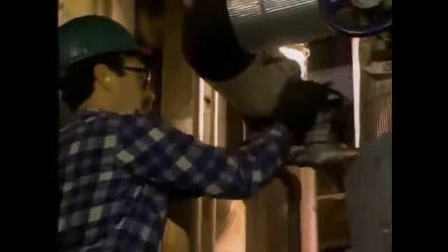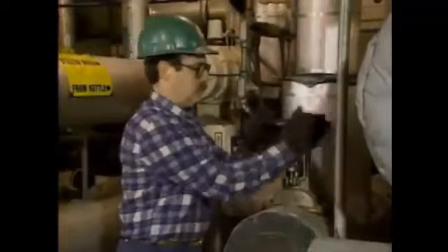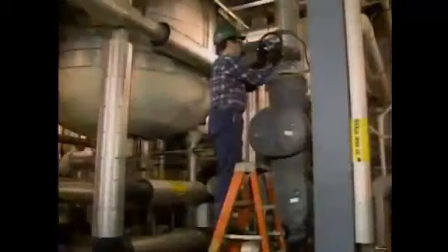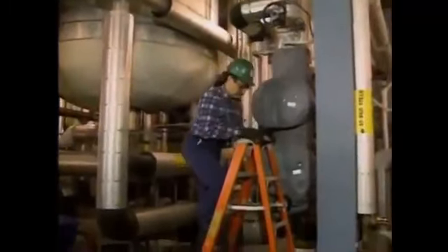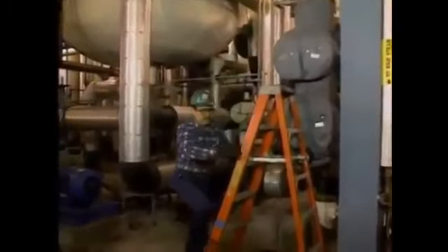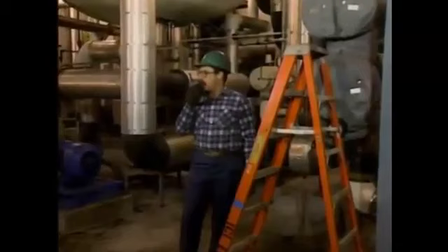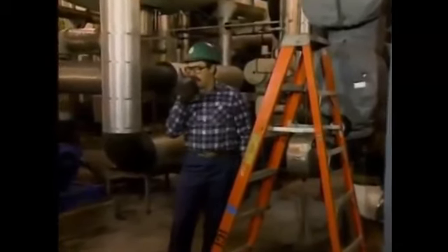When the tube side is filled, the operator closes the vent valve and opens the inlet valve the rest of the way. Then he opens the outlet valve. At this point, the startup is complete and the heat exchanger is in operation. After the operator reports to the control room that the unit is in operation, the control room establishes flow through the unit.